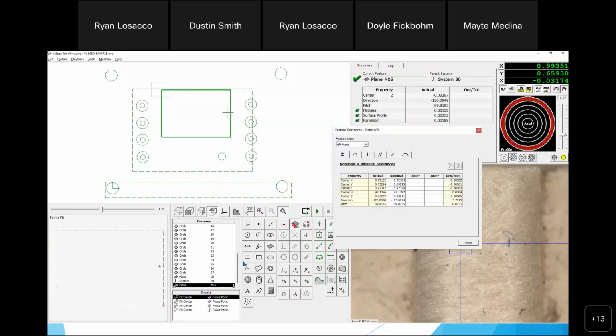So now I need to tolerance this profile. I need to tolerance as many basic dimensions as my blueprint tells me before I tolerance my profile over here. So if I come here, I have that Z height. That Z height is supposed to be, let's say, 032. That's what my blueprint says. Basic dimensions don't get tolerance. We just say what the nominal, what the perfect location is. So now MicroView knows where to place that perfect profile guard band on that surface.